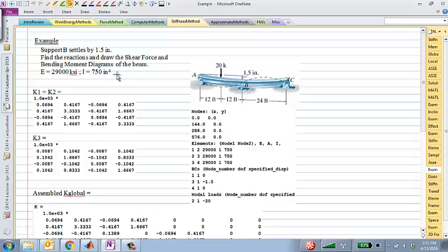So how should we proceed? First of all, if I have given you the Matlab codes, and I asked you to solve this problem, how do you do it? Yeah, we try to come up with an input file for this. So for this problem, how many nodes should I have? 3 or 4? 4, because there is a load in here. Technically, you can do it with 3 also, but I'll talk about that a little bit later. For the code that I've given you right now, yes, you do need at least 4 nodes: 1, 2, 3, and 4.